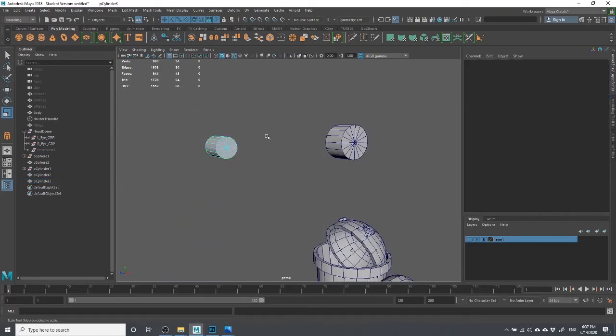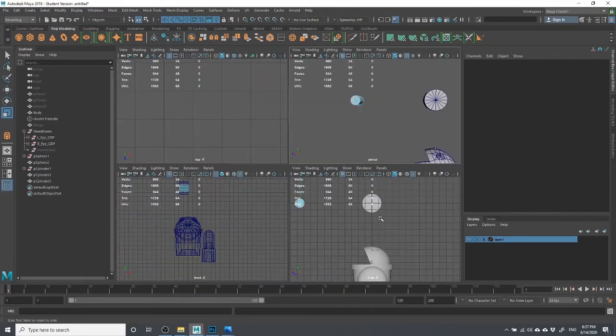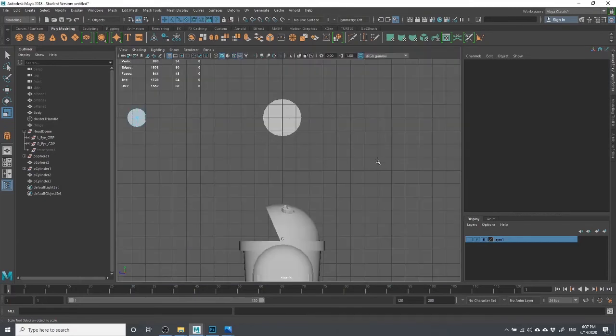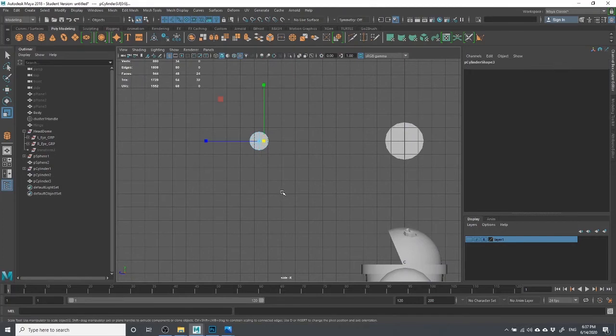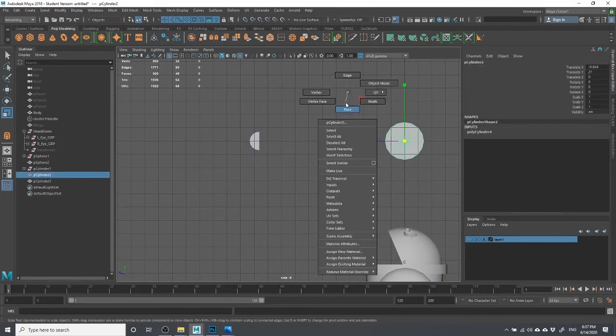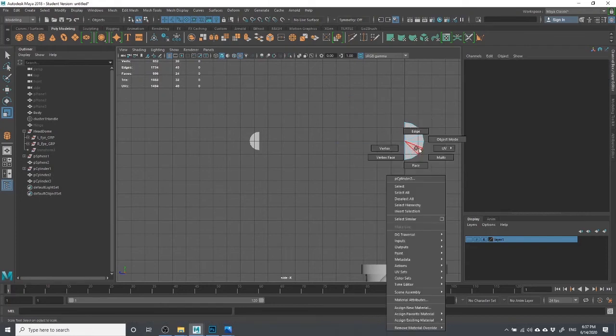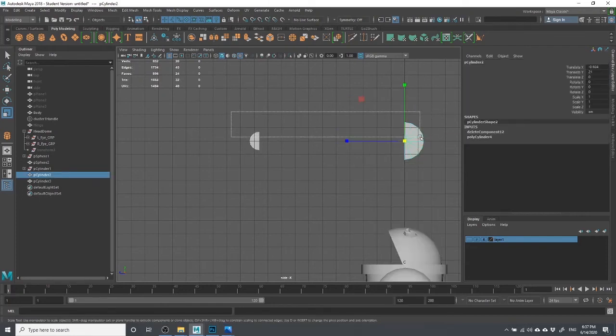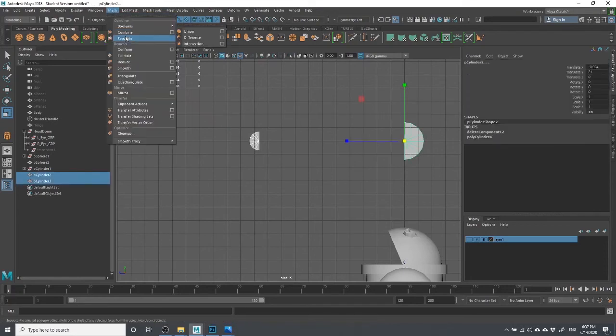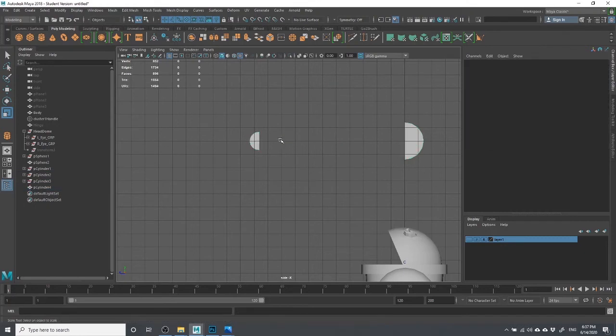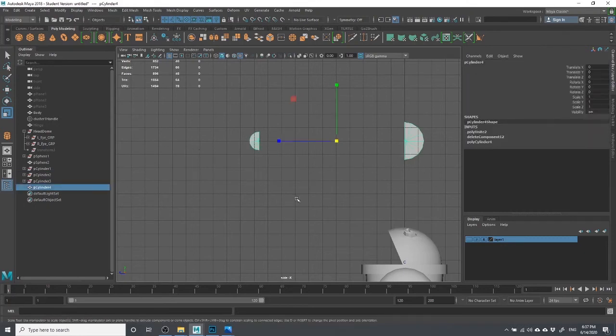All right, here let's start editing this stuff. Long story short, you guys, what I'm going to do is just chop this off. And let's take this guy, I'm going to chop this off, and I'm going to build a bridge between the two, like so. The first thing I need to do to build a bridge at all is I've got to combine them. So I'm going to go to Mesh, Combine. When I combined them here, let's call this finger. I'm going to double click and just call it finger, just as an example. It could be whatever you want.